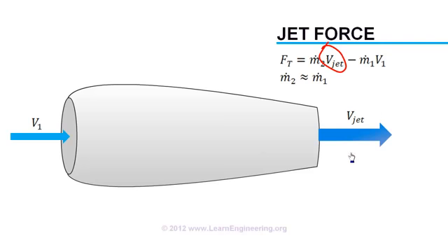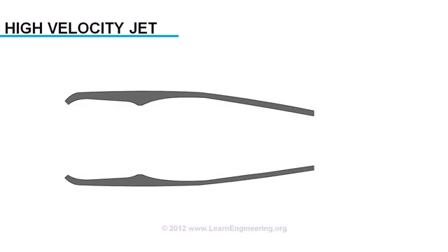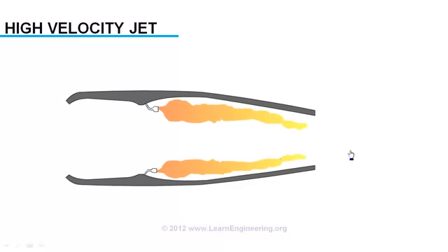The million-dollar question: how to produce such a high-velocity jet continuously? We will produce it by a combustion process, by injecting fuel into it, which will produce flames with very high velocity. But for a sustainable combustion process, we need the inlet air to the combustion chamber to be at high temperature and pressure. This is achieved with the help of a diffuser plus compressor arrangement.